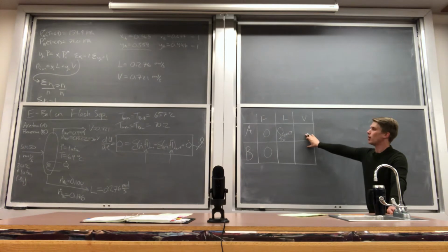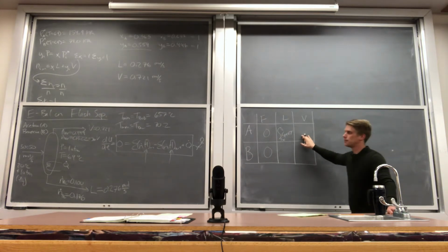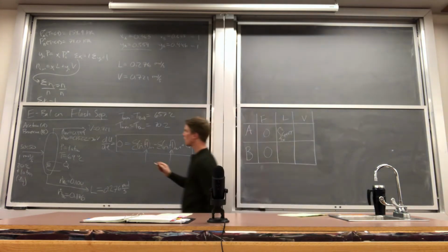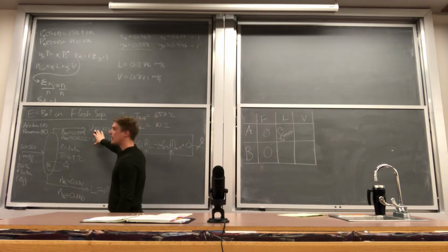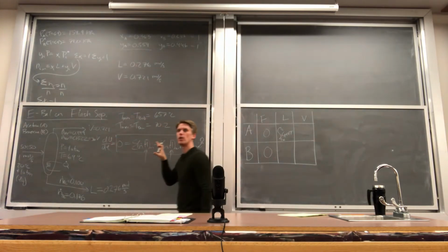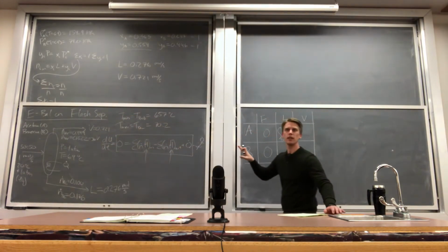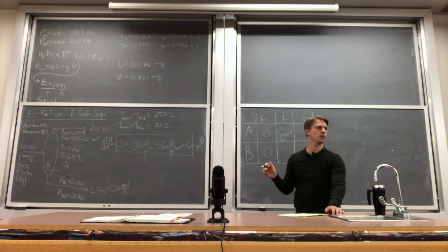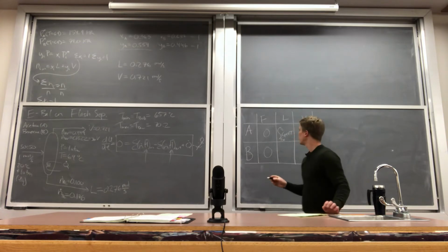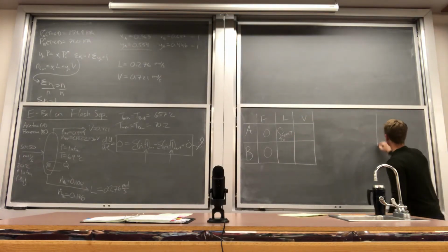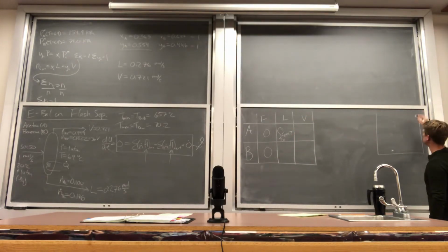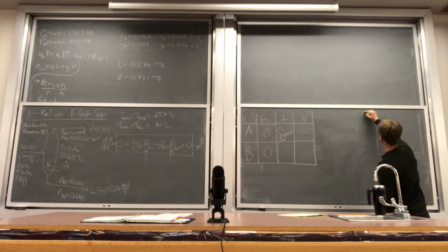Well, so for the vapor one, there's a couple of tricky issues here, right? In a flash separator, we are never going to be using the normal boiling point of any of the fluids that are in the back of the book for the heat of vaporization. Because if we look at a TXY diagram, I'll call this Z of acetone here.